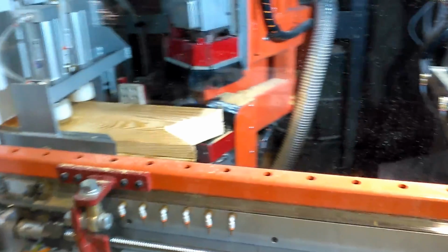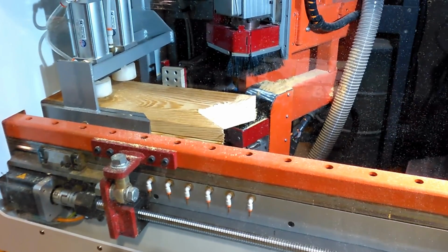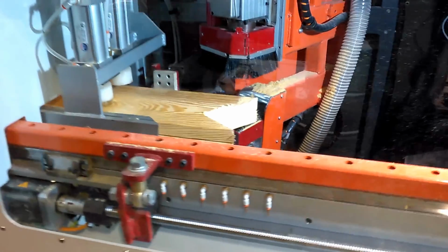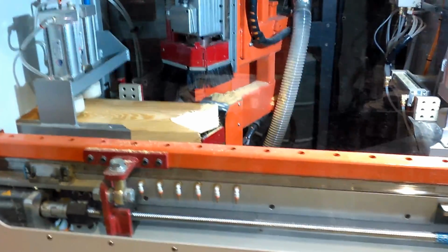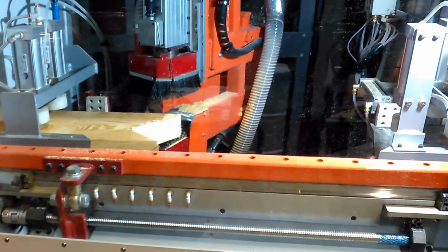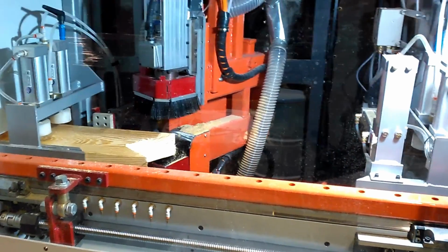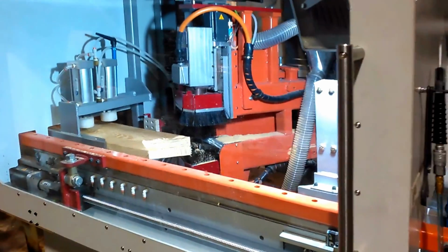One piece of information. This, like I said earlier, is a piece of 1.5 by 9 1/4 board. Feed rate could be sped up a little bit on this product. Again, these are resharpened tools. If you did something thinner, the feed rate could be substantially higher.